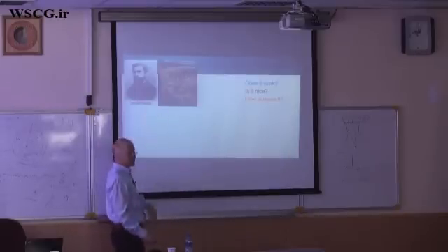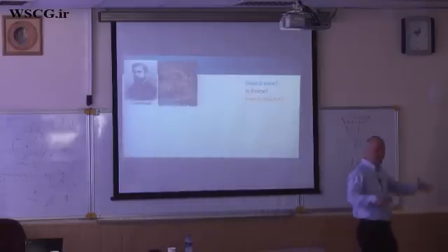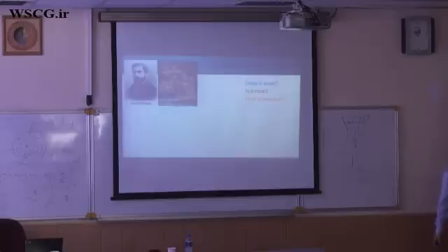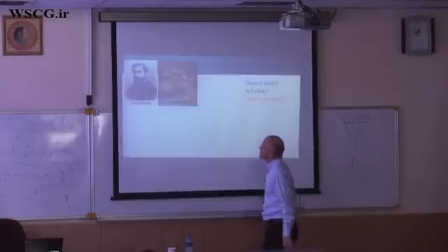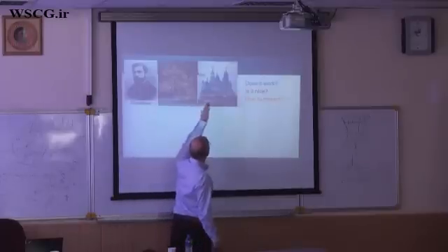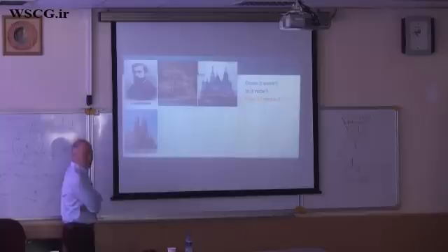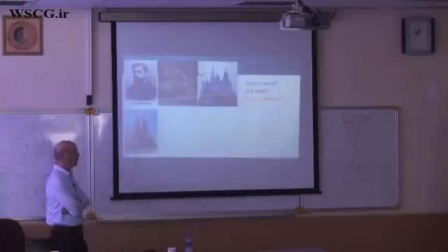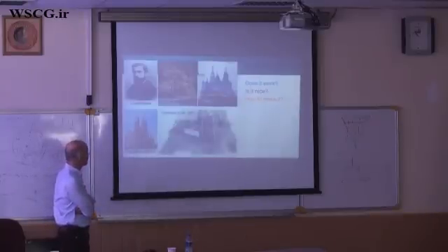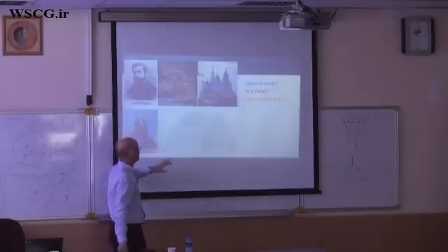So he had these famous hanging models. And if you take this hanging model, if it is in force balance with tensile forces in the first place, if I turn it around, it is in force balance with compressive forces after turning it around. And this was somehow the basics of his designs, like this famous Sagrada Familia, which is a very complicated, geometrically very complicated design in Spain, of course, and is still, as far as I know, not really completed. So they are still working on it.